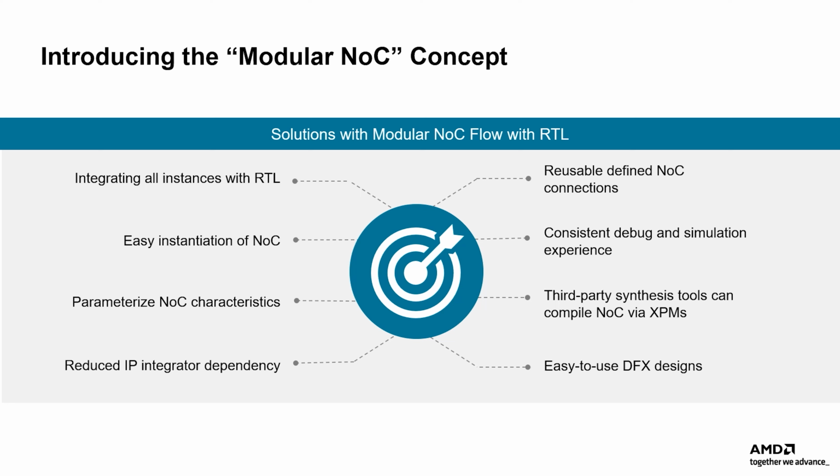Defining NoC connections per module and reusing a module in different system-level projects. Keeping everything consistent without affecting the debug and simulation experience compared to the current IP integrator-based NoC solution. Third-party synthesis tools can compile the NoC via Xilinx parameterized macros, XPM instantiations.